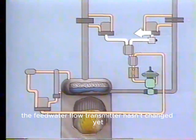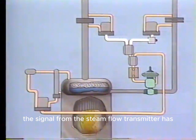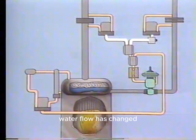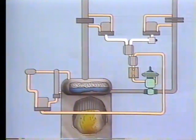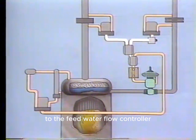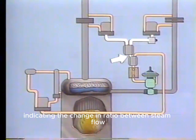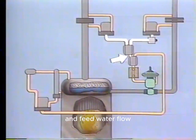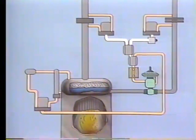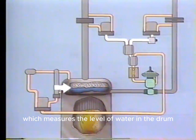Although the signal from the feed water flow transmitter hasn't changed yet, the signal from the steam flow transmitter has. Therefore, the ratio between steam flow and feed water flow has changed. The ratio controller sends a corrective signal to the feed water flow controller. This signal reflects the change in ratio. The signal indicating the change in ratio between steam flow and feed water flow is one of the inputs to the feed water flow controller. The other input is from the drum level transmitter, which measures the level of water in the drum.